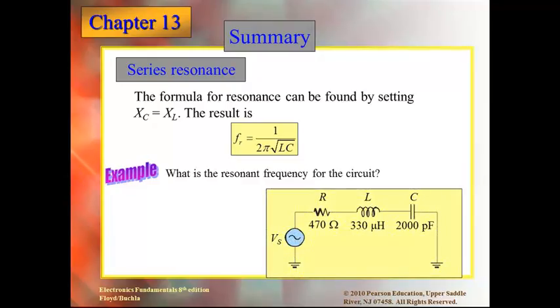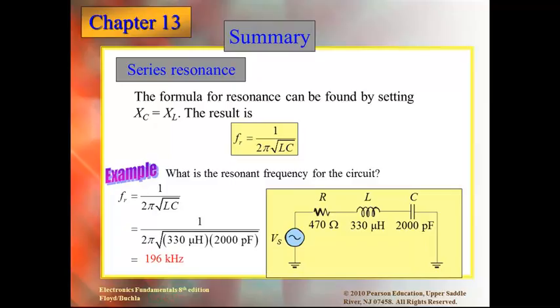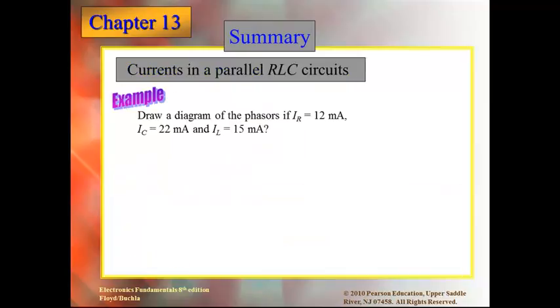And so here, again, going back to our problem, using those figures, we can calculate our resonant frequency at about 196,000 hertz. How do I generate 196,000 hertz? Frequency generator, right, or function generator. Not practical for everybody to have function generators at their house to keep things balanced or at a business. We're going to use 60 hertz.